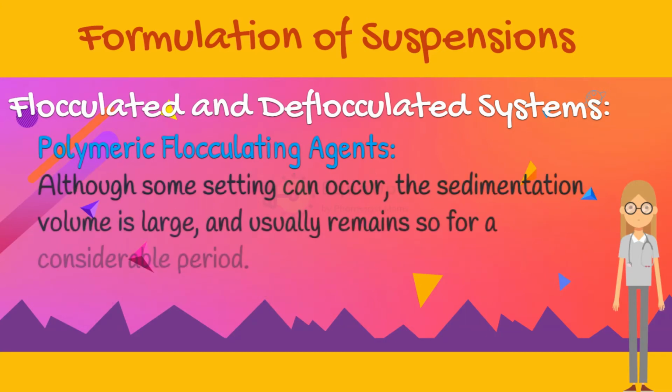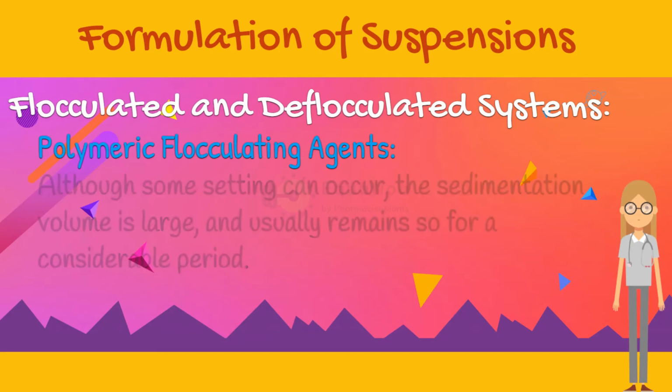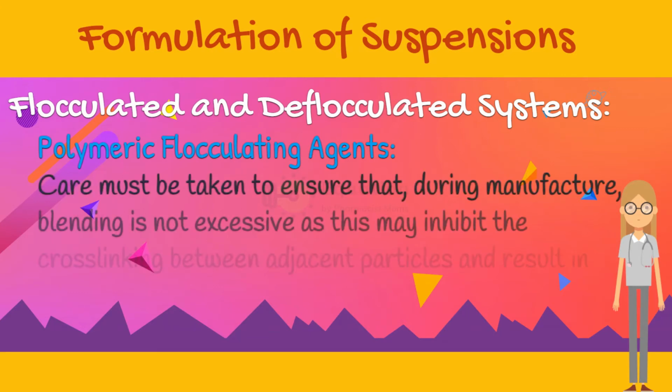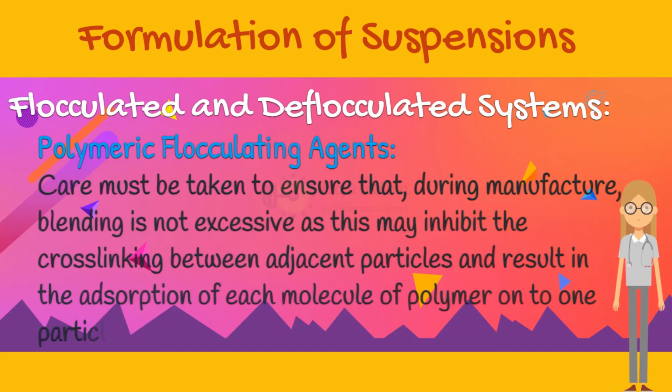Although some setting can occur, the sedimentation volume is large and usually remains so for a considerable period. Care must be taken to ensure that, during manufacture, blending is not excessive, as this may inhibit the cross-linking between adjacent particles and result in the adsorption of each molecule of polymer onto one particle only.